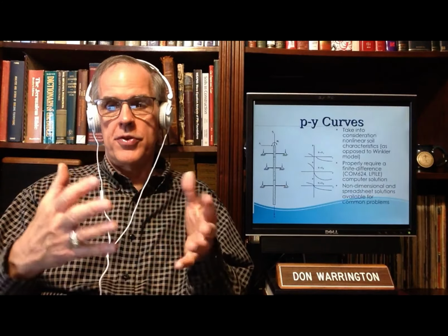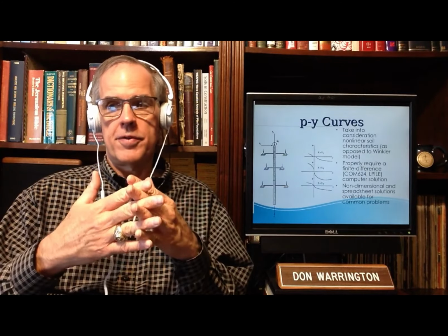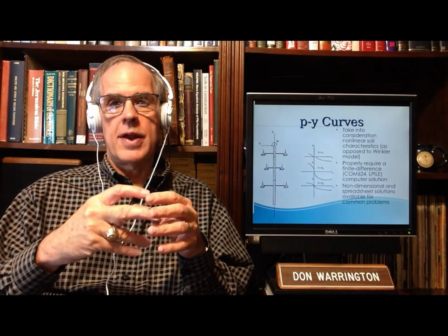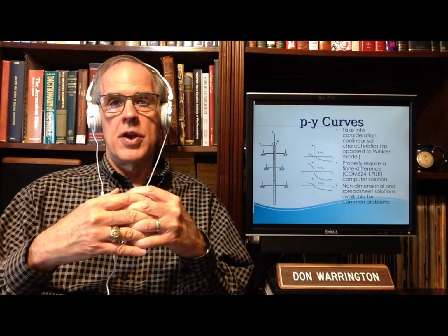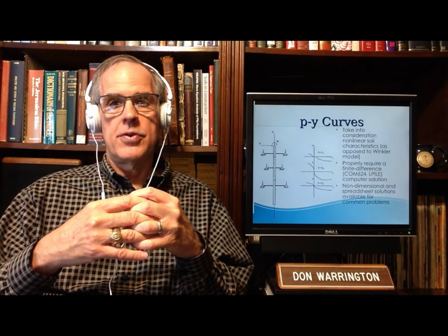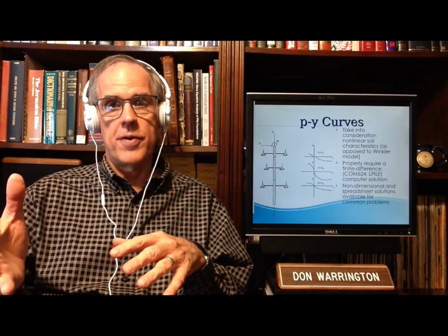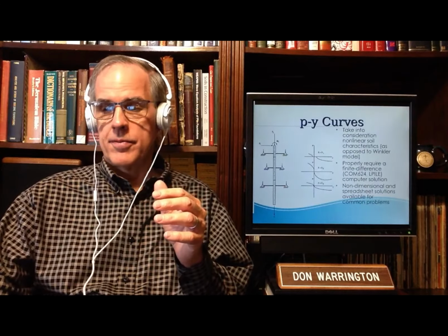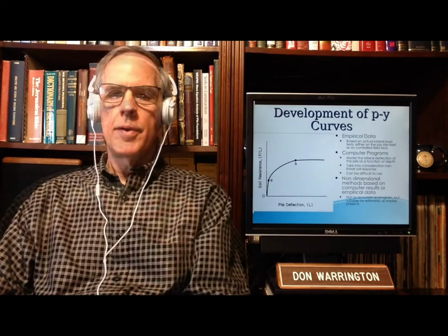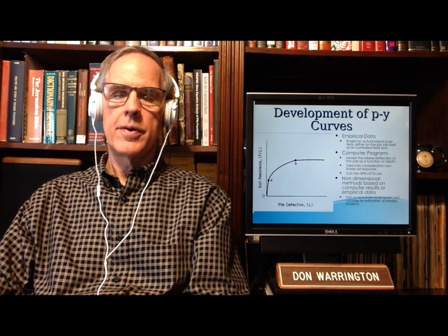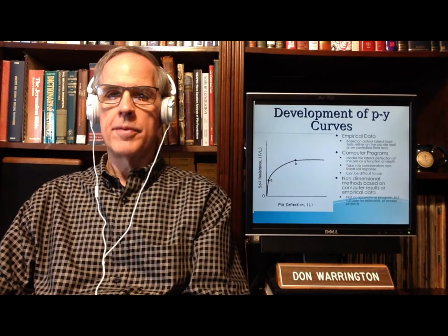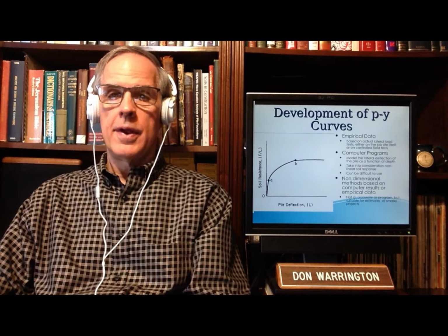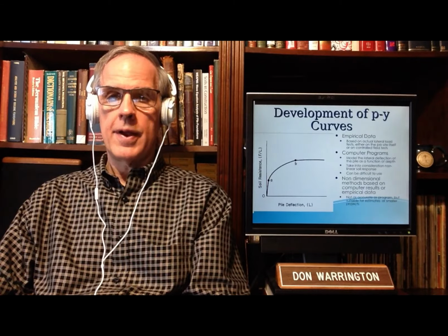And if you throw those into a numerical model, which they used, a finite difference model, they determined they would actually be able to estimate the response of the soil in conjunction with the pile to its lateral loading. When they obtained their data from their empirical tests, they applied these to the model, and of course the pile was suitably instrumented, and then they developed the PY curves from that.